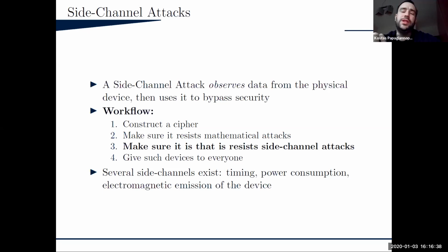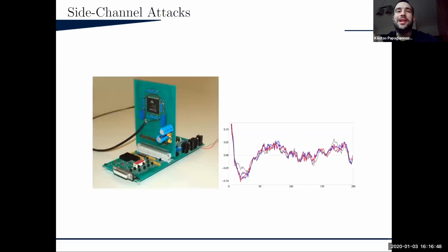First, we discussed execution time. There are even more popular side channel techniques that involve power consumption and electromagnetic emission of a device. So typically what I like to show is a simple device like that. Here you can see a microchip, and here you see a small antenna that rests on top of it. And while AES is being executed, the power consumption is being measured, and you can see it in the signals here. In this context, it's actually quite interesting to see that even small variations and statistics can help you find the secret key just by observing those fluctuations over time. And we do have assignments of that during our course.